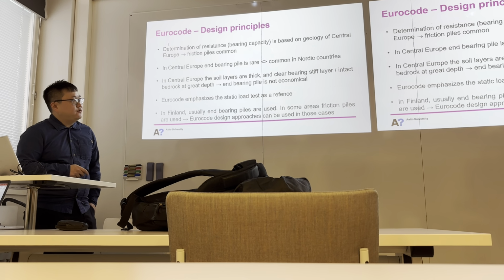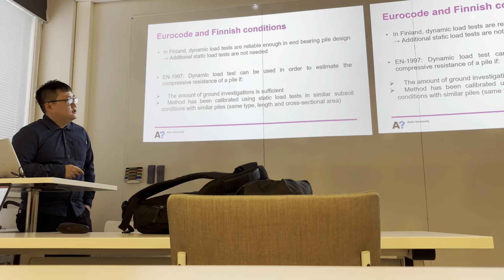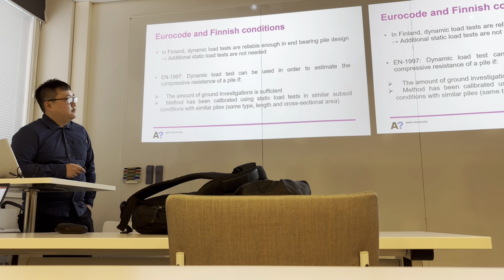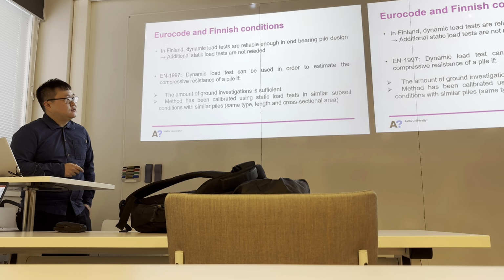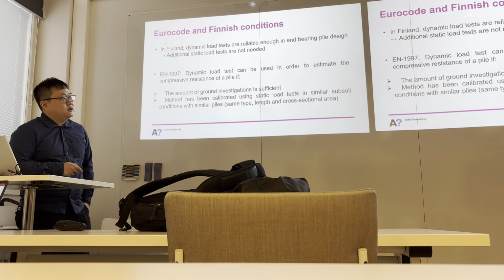In Finland, the dynamic load tests are reliable enough for the design of the end-bearing pile, and additional static load tests are not needed. According to Eurocode 1997, the dynamic load test can be used to assess the compressive resistance of the pile when we have enough ground investigations, and the method has been calibrated using static load testing in a similar environment.